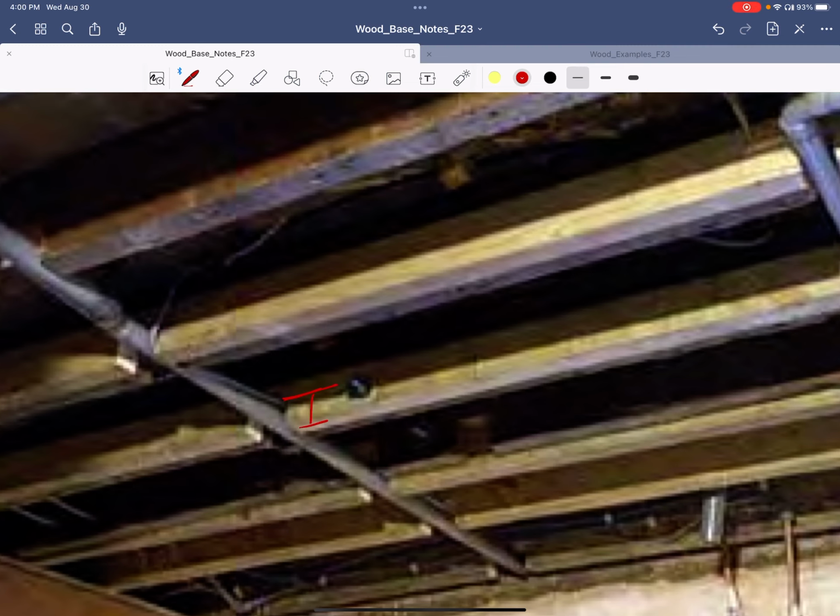these notches. That's more than a 6. It looks like a half. I don't know how high this goes up into here. And you might as well have not even used that depth of beam when you cut off half of the depth to make a notch in it for piping and things. So really this has to be done carefully, or there has to be special reinforcement pieces in here, or a doubling up or something like that.